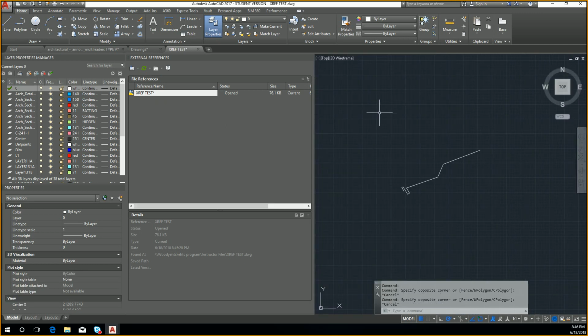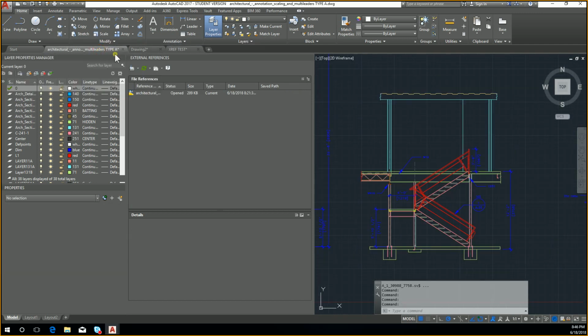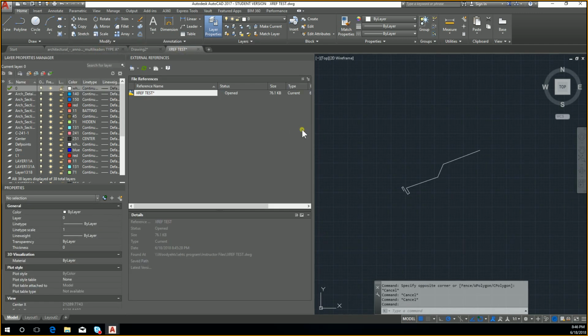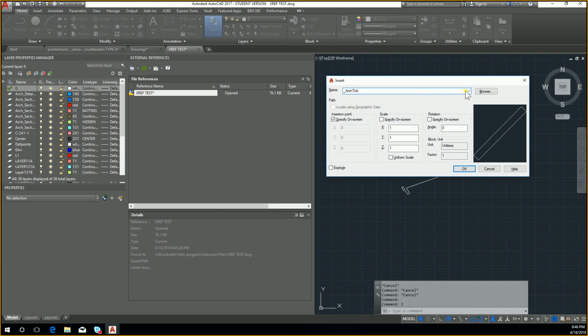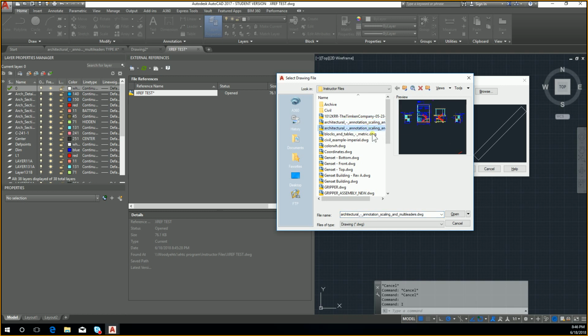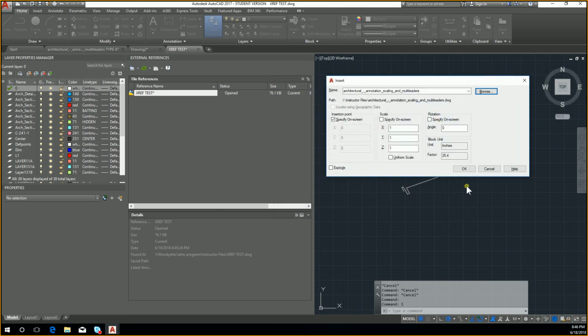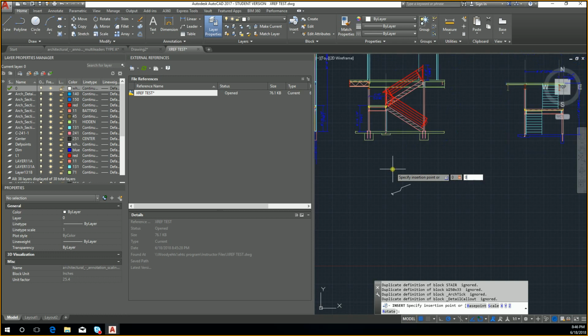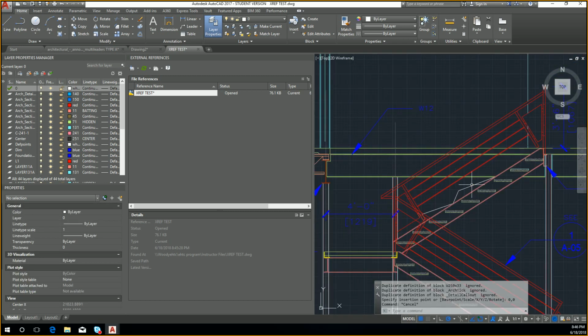So now, really important also, practice doing an import where you have updated that original block and understand how you can redefine that block as well. As I'd mentioned before, let me just bring in something. I'm going to go ahead and import something again. I've now imported this piece here, at 0, 0. So that's my original import.